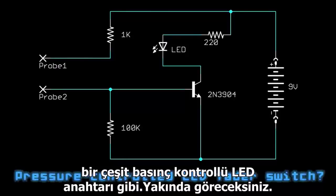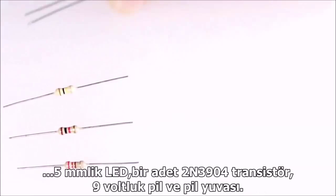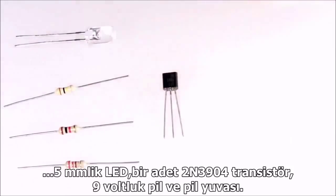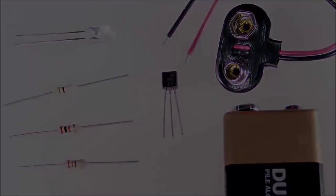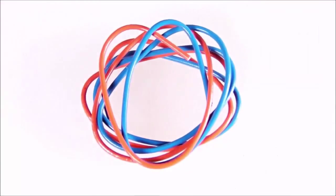Well, you'll see. To build it, you'll need a few parts. 3 resistors, a 220 ohm, a 1K ohm, and a 100K ohm. Also need an LED, 5mm one is good, a 2N3904 transistor, 9-volt battery, and a battery clip. Oh, and you also need some wire, too.